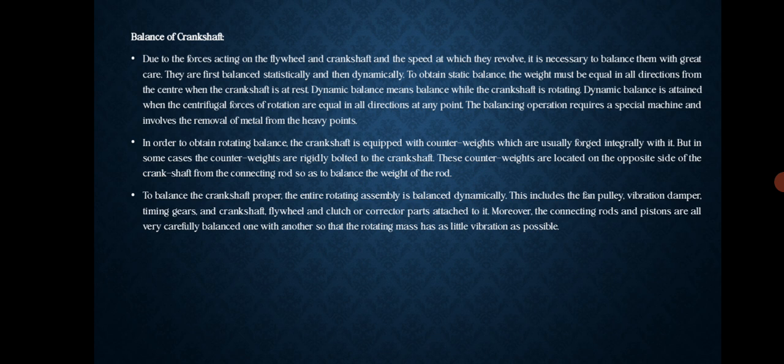Next is balance of the crankshaft. Due to the forces acting on the flywheel and crankshaft and the speed at which they revolve, it is necessary to balance them with great care. They are first balanced statically and then dynamically. To obtain static balance, the weight must be equal in all directions from the center when the crankshaft is at rest. Dynamic balance means balance while the crankshaft is rotating.